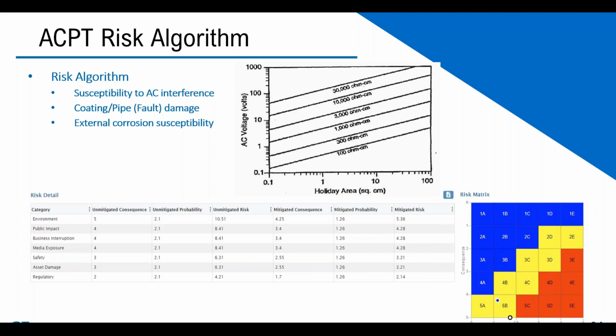Usually about a meter, maybe less than a meter, or just over 3 feet, is the key. And of course, it's still susceptible to wet and dry cycles. So soil resistivity does change with seasonal variations, with flooding and things of this nature, other issues. But we could look at where the pipe would be susceptible with simple calculations.